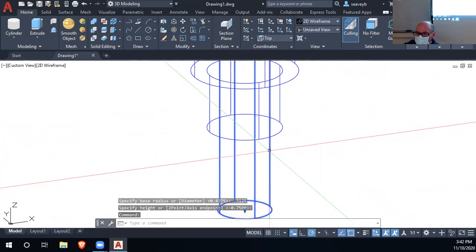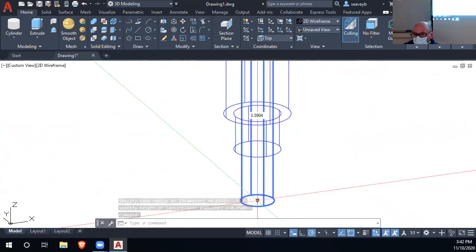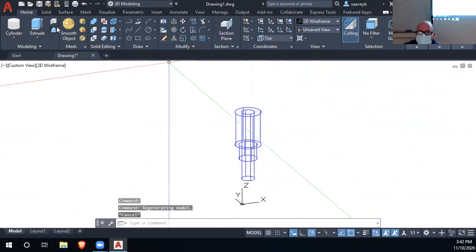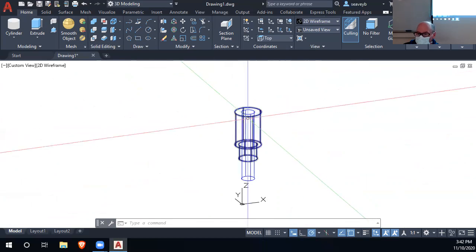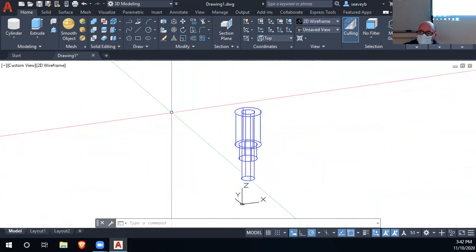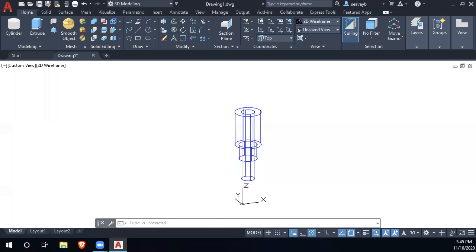So this thing's like, you can edit cylinders and stuff too. This thing's 3.59 inches tall downwards, right? But I don't care because I'm going to use the solid subtract tool to subtract the inner cylinder from the outer one. Now I want to show how to use the solid subtract tool. So I'm going to subtract basically this